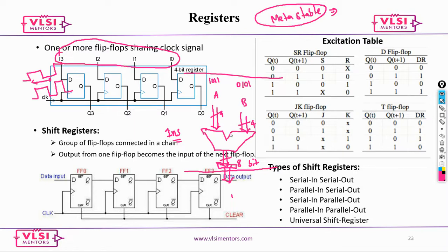I'm just trying to make you guys understand why you need registers in the design first of all. You might have gone through registers as a topic in college, but where it is used and why you need them, I'm just trying to give you the practical side of it. So when I say ALU, it can do any kind of operation, say addition, subtraction, multiplication, etc. When your ALU is performing that operation, your data has to be constant. So how can you ensure constant data? You have to send it through a register, controlled with the clock.